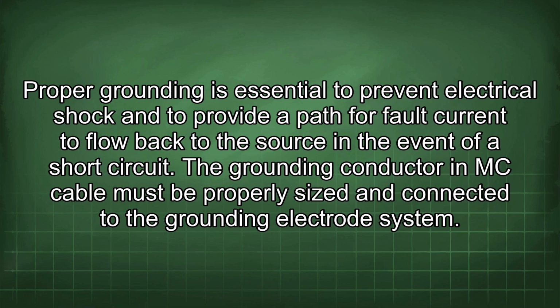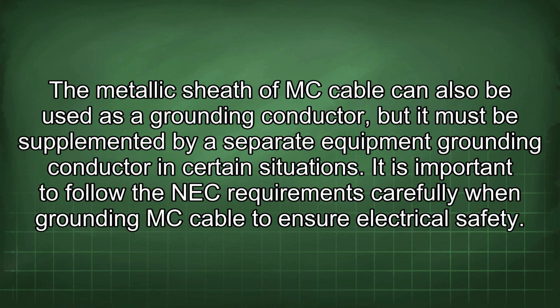The grounding conductor in MC cable must be properly sized and connected to the grounding electrode system. The metallic sheath of MC cable can also be used as a grounding conductor, but it must be supplemented by a separate equipment grounding conductor in certain situations.